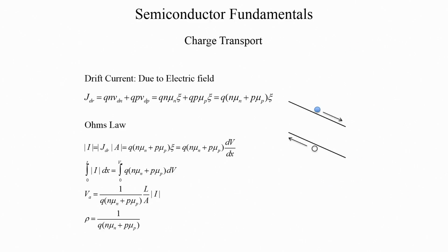So we now consider mechanisms of charge transport. So far, if we take a summary of everything we have done, we have established a method to count the number of carriers in the conduction band and the number of holes in the valence band. In order to count them we established what the density of states was, we established what the Fermi function was, and with these two we could evaluate the values of n and p.